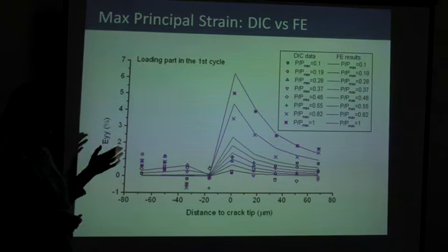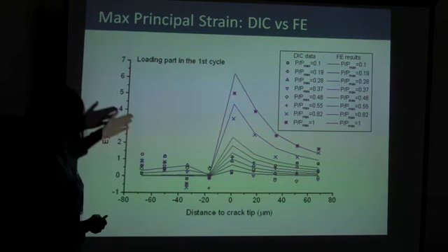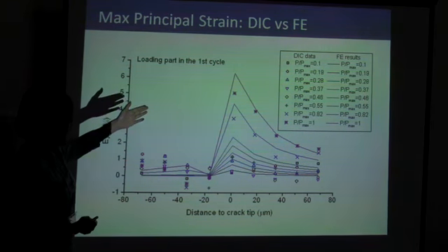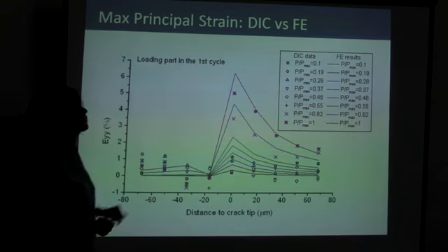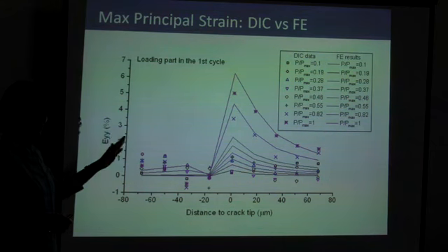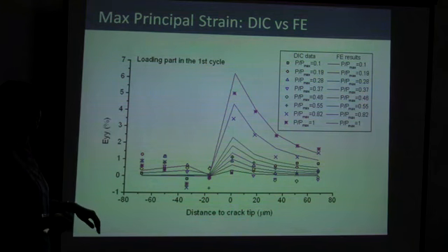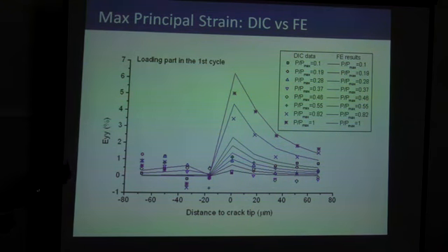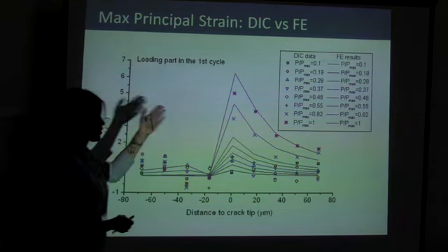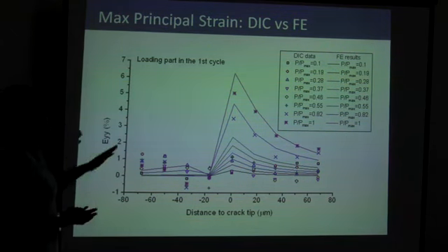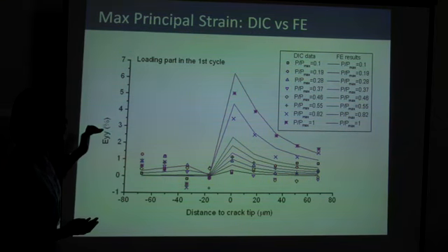Now, at first glance, if we look at the high load level, for example, part 2, the crack tip measured value correlates quite well with the FE result. By the way, the FE result has no closure because we only simulated for the cycle. So if the closure has no influence, that would mean the first two should have no influence. But what we registered with the closure measurement is, I think, up to 0.46.